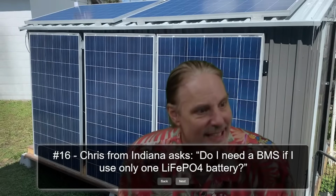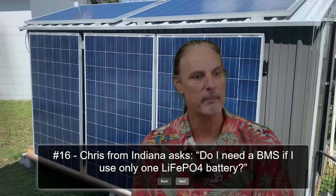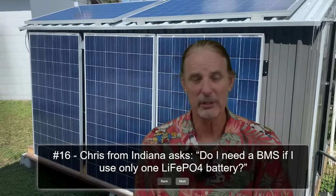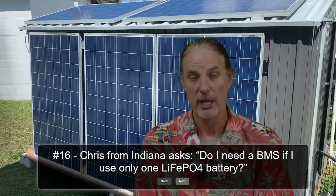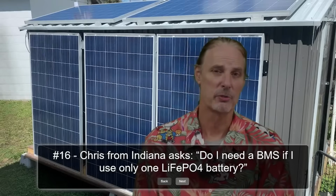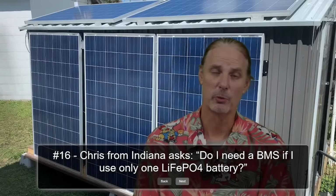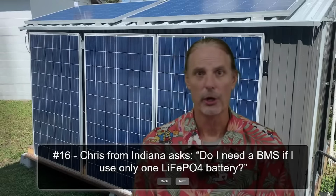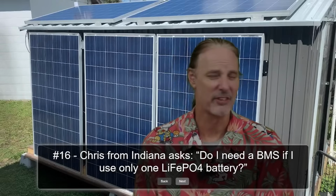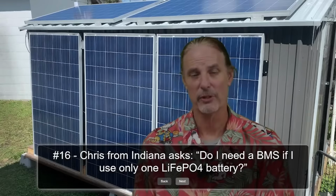Chris from Indiana asked, do I need a BMS if I use only lithium iron phosphate battery? And the answer is the lithium iron phosphate battery should have a BMS, and if you are building a DIY battery without a BMS, I would say no, stop, put in a BMS. The BMS is there to protect the battery and you. It protects you against massive discharges. It protects you against charging too much. It protects the individual cells. Can you do it without it? Sure, you can do it without it. You can also jump off of a building, but that's not advisable. So please, if you are building a battery, it needs a BMS for the lithium iron phosphate.